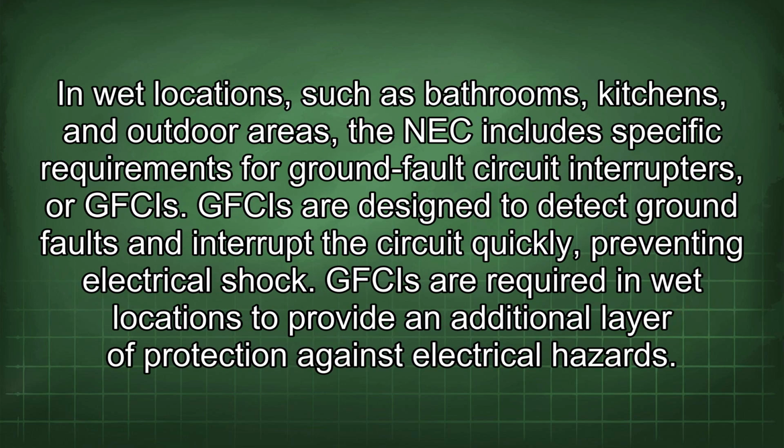In wet locations such as bathrooms, kitchens, and outdoor areas, the NEC includes specific requirements for ground fault circuit interrupters, or GFCIs. GFCIs are designed to detect ground faults and interrupt the circuit quickly, preventing electrical shock. GFCIs are required in wet locations to provide an additional layer of protection against electrical hazards.